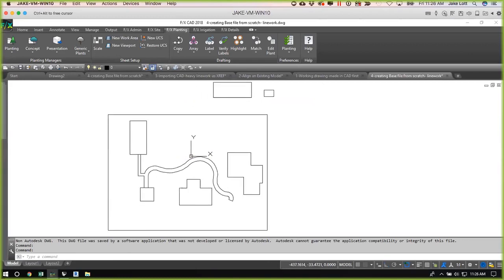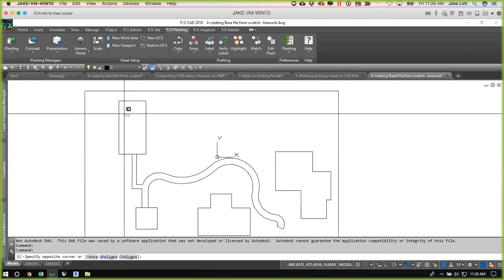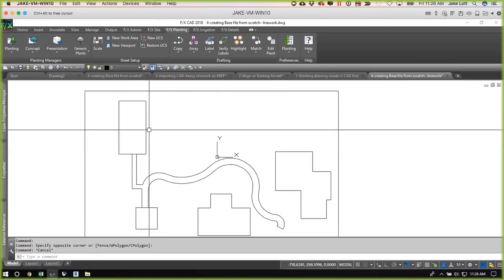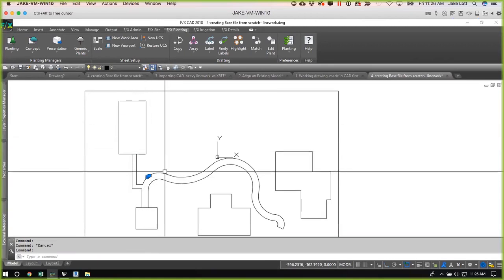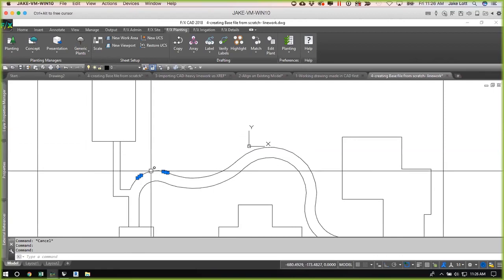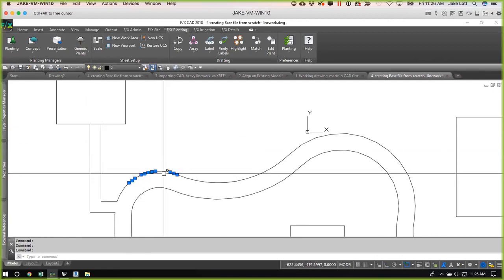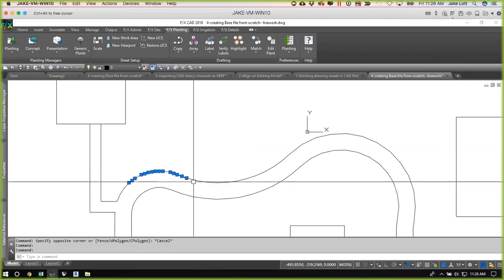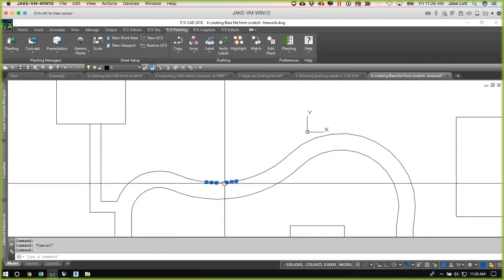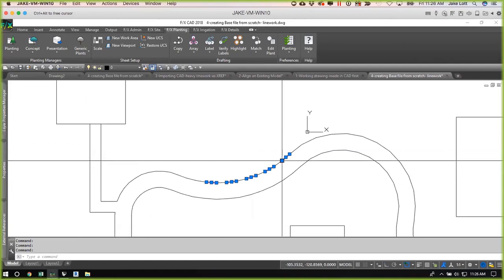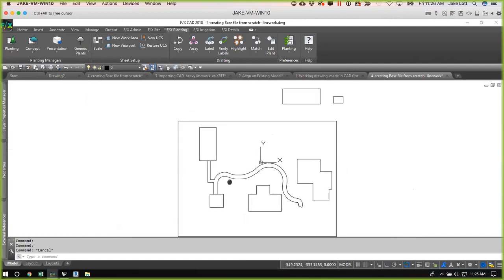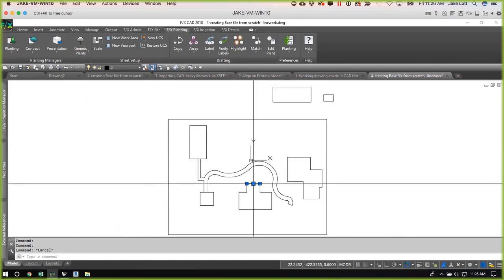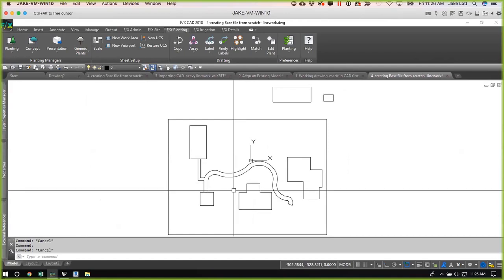But there's our line work, and you can see that it is just single lines that we got going on here. Now, here's the trade-off: when you do things in SketchUp, it is going to bring it in by every line segment. So those arcs are busted up and stuff like that. So it is a little bit of a messy way of getting some line work in here.